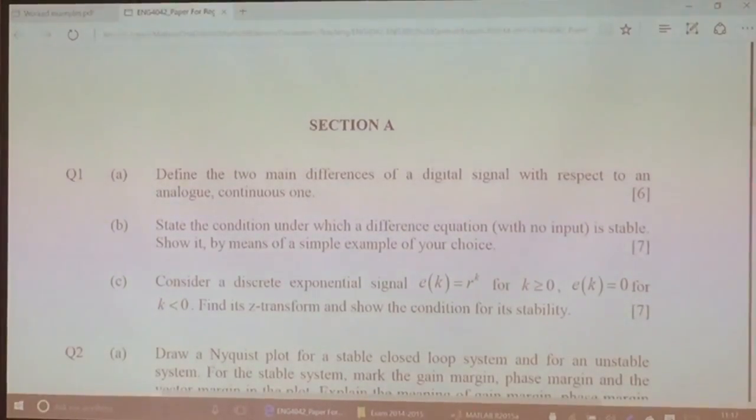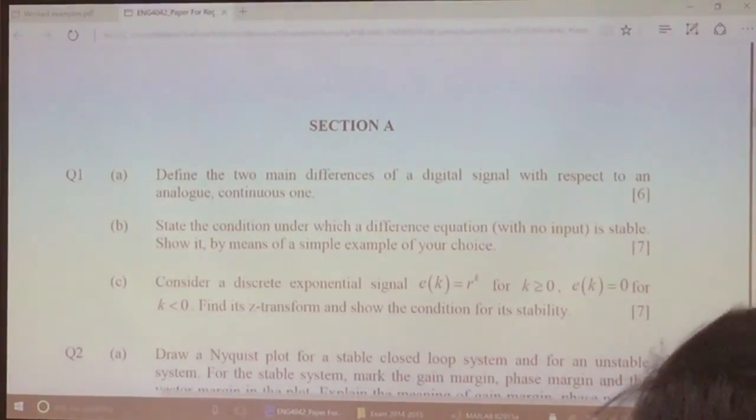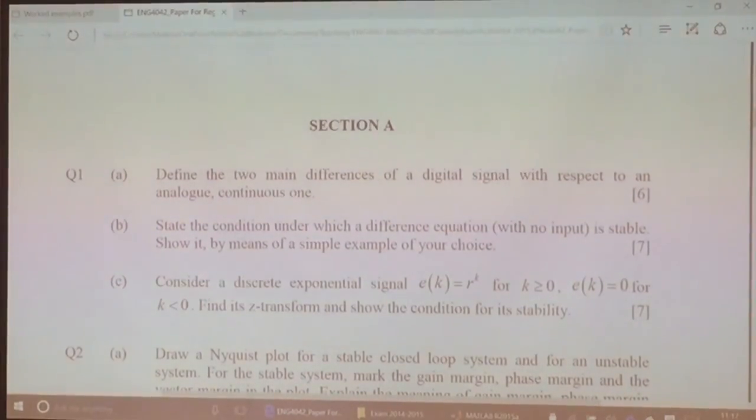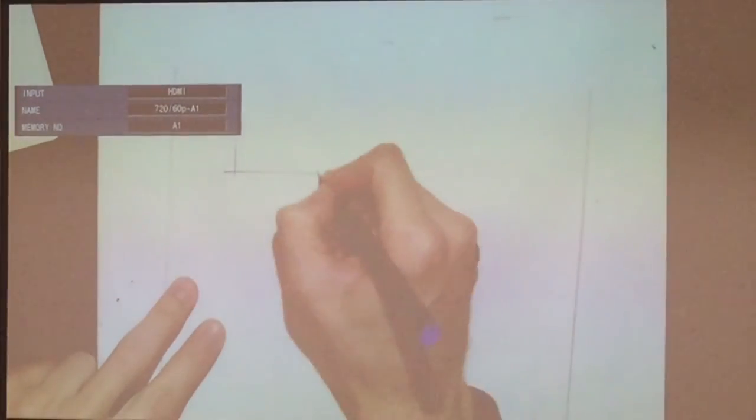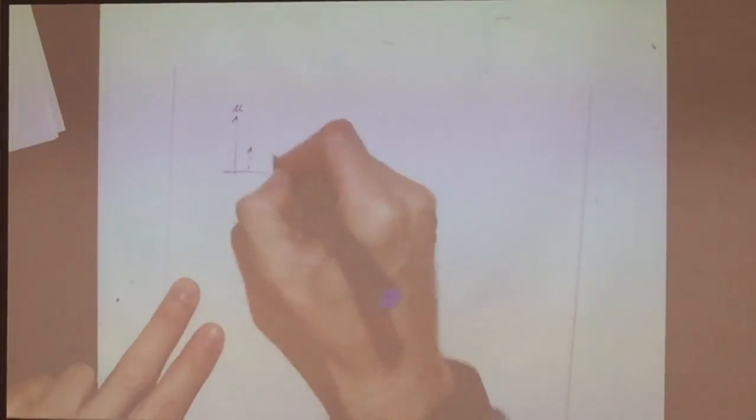Discretization is something that happens in time. It means that you have discrete samples in time and not a continuous function of time. Quantization instead is a discrete set of values for a signal, and this is related to the word size of the computer you're using. If you want to make it visual and help your description a bit, a graph like this would help a lot. So you have time, and you have your signal. A discretized signal is something like this, right? Discretized in time.